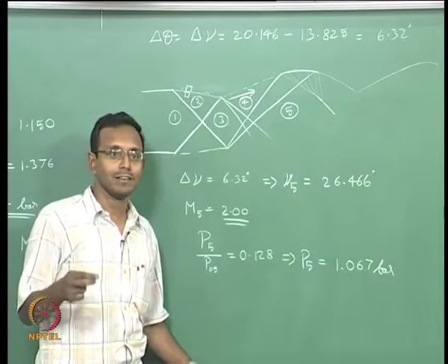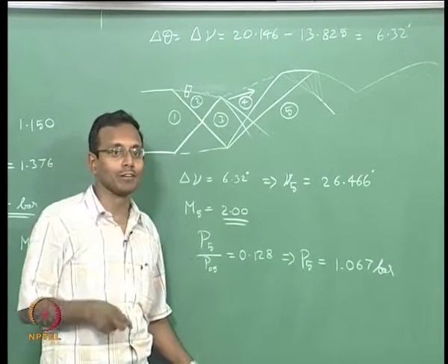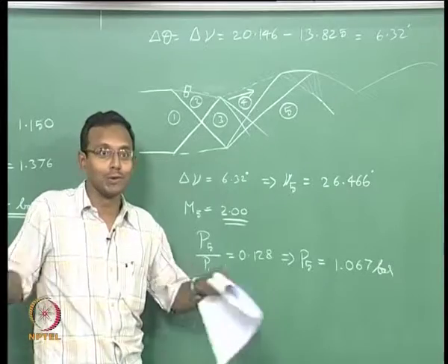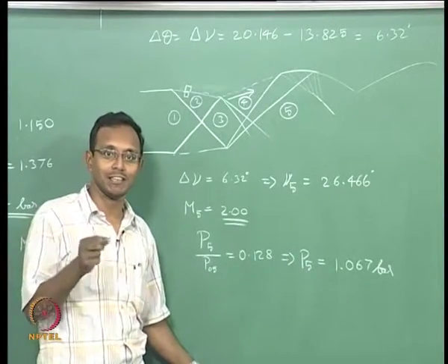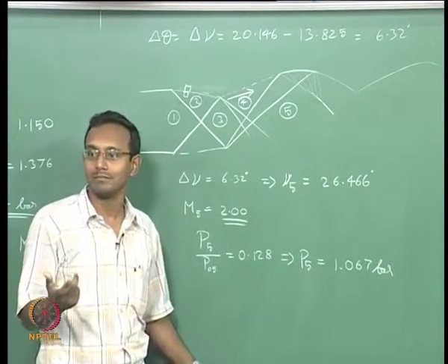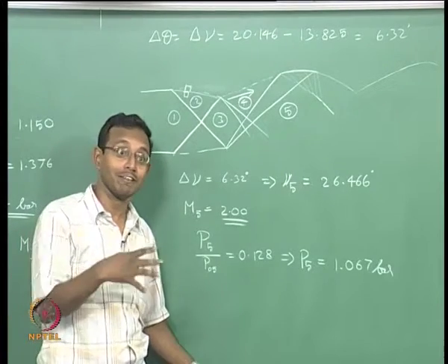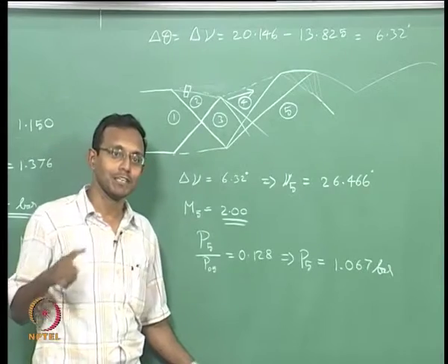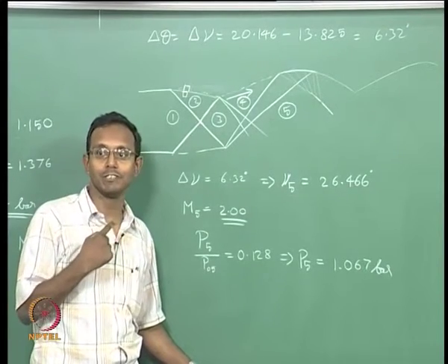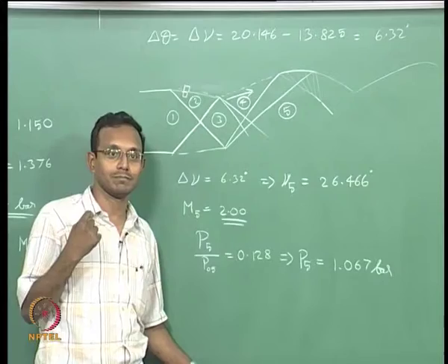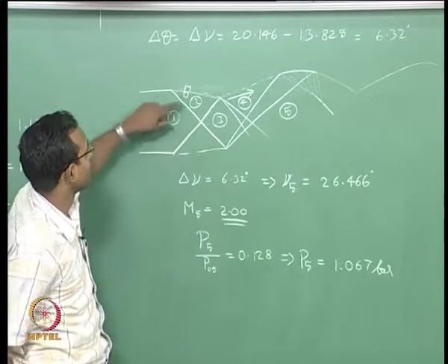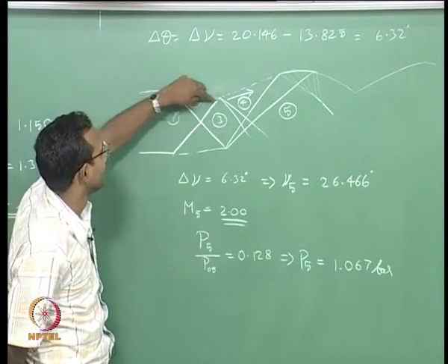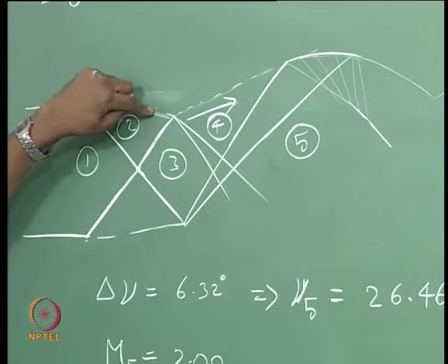It is like you put a drop of ink in water, immediately it diffuses out to all the regions, and finally you do not see any ink in water. The whole water has all the ink dispersed everywhere equally, until the diffusion finishes. Similarly here, viscosity diffuses the vorticity. The only place where you will see a serious amount of vorticity is this edge, the jet boundary alone.